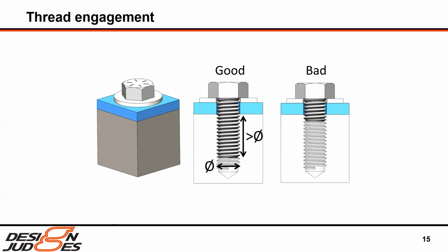And even in a lot of critical applications, they'll actually use these threaded inserts. This one's like a key insert where you have these pins that you drive down in to lock it in place. And that'll make your joint a lot stronger. And of course, these are just a general rule, analyzing the true strength of the material and the stresses in it for any critical application is really, really advised.